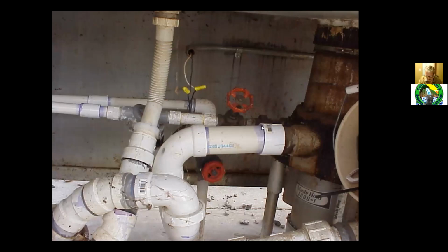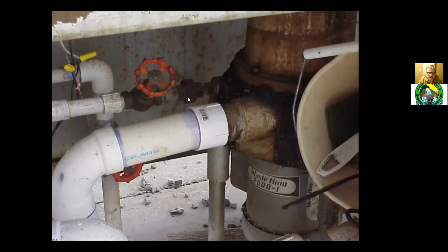It might be a little hard to tell from these pipes, but they're all connected on both sides, providing a cross connection right into that pipe. So that's the drain from the sink that's connected to the drain here, which is connected right to the potable water supply.